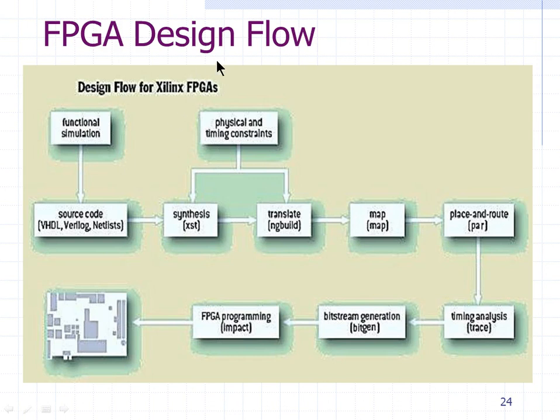This is a typical flow, a design methodology as we call it, for Xilinx FPGAs. It is also true for Intel FPGAs, and it will also be true mostly for all ASICs. Before we start writing Verilog for anything, we do something called design specifications. Normally a team of software and hardware architects will do that. They will decide what needs to be designed, and all that is put into a document called a design specification document.